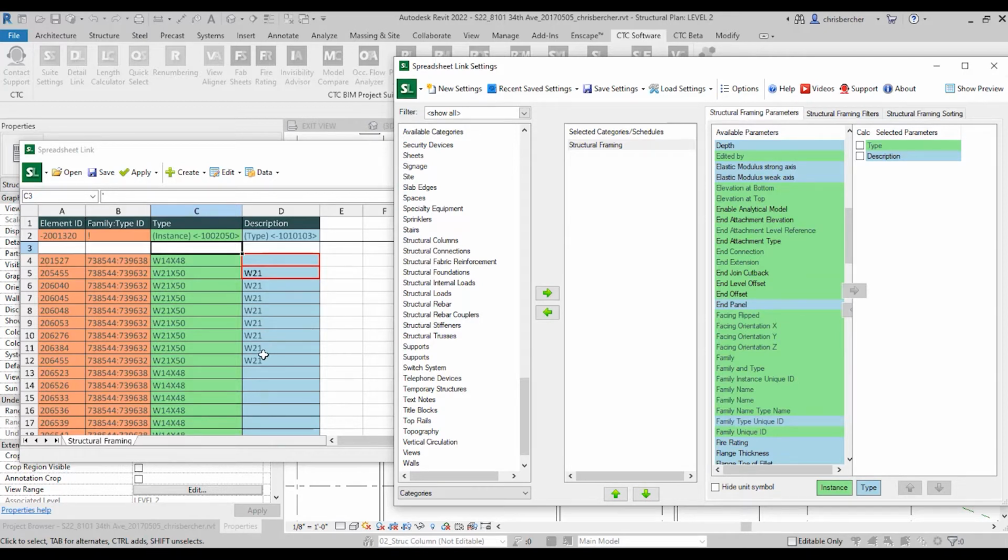When you add those two fields, since we're using a formula, Spreadsheet Link has a function in here for calculations. We have a little checkbox here. And what this does is, if this box is checked and a cell gets a formula entered, that will automatically take that formula and copy it all the way down the line for all the different cells that are available in this column so that you don't have to do that yourself.